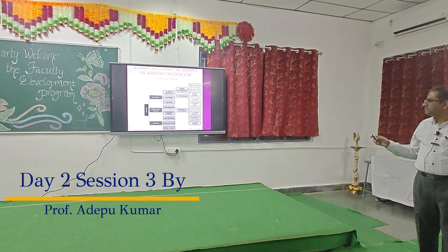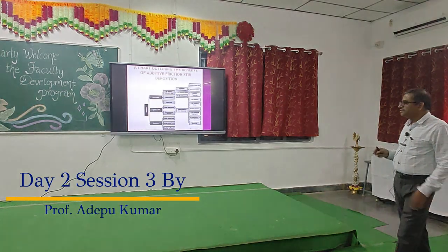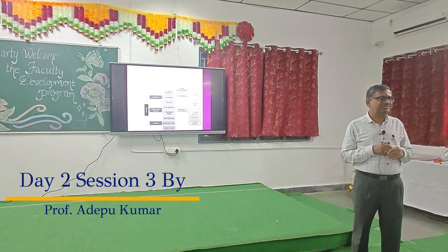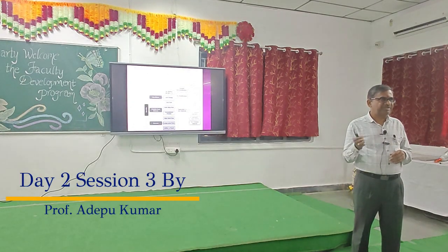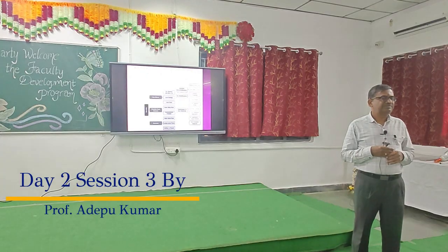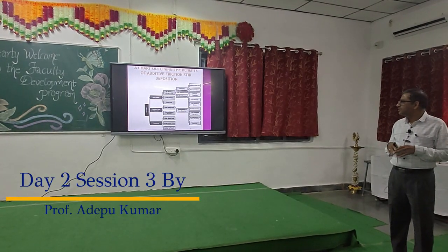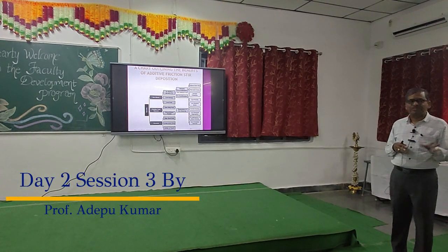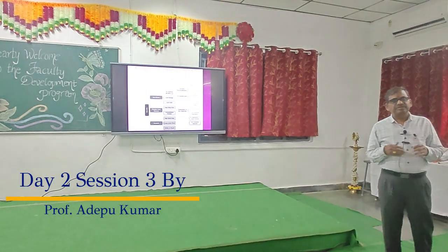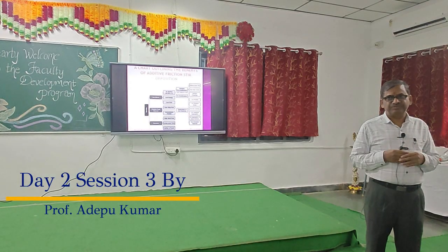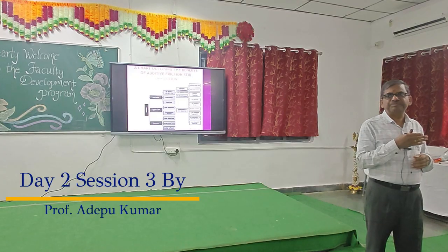Just an overview of this slide: you can get better mechanical properties, less porosity, less energy, and compatibility with dissimilar kinds of materials, and no gases are required to protect against contamination from the environment. And the stresses induced in the material are less, because in fusion based additive manufacturing you are melting the material and allowing it to solidify. During the solidification process, that is a rapid solidification process,